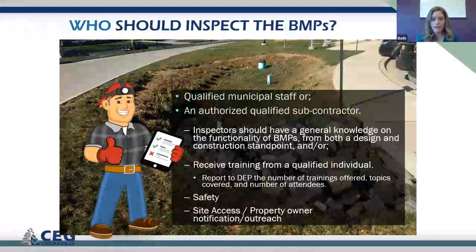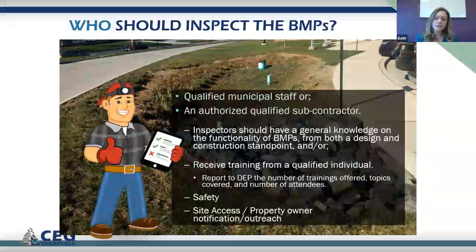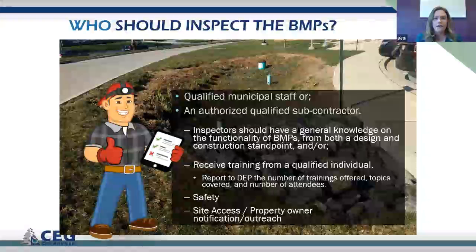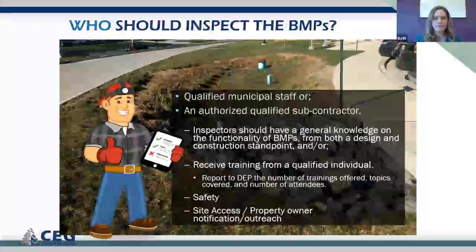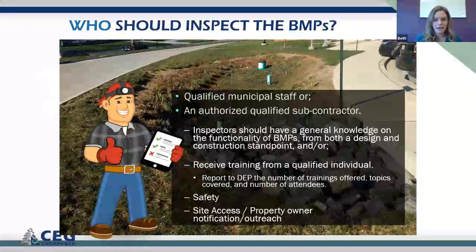So qualified means having a general knowledge of the functionality of BMPs from a design or construction standpoint, or having received some sort of training. Ideally, the training that they have received should be both classroom training as well as field training. And then also, when you have your inspectors going out to the site, you want to consider safety. And do you want one person or a two-man inspection crew?